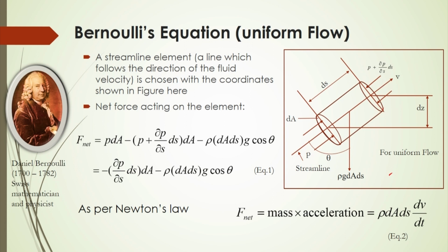So, finally, the net force is minus dou P dou S ds into dA minus rho dA ds g cos theta.